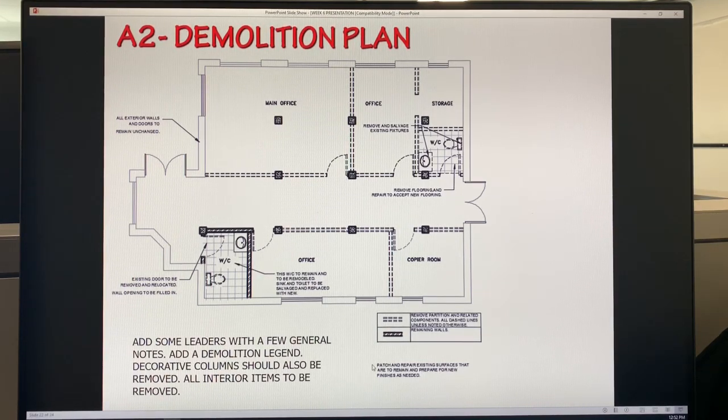Also incorporate some notes like this: patch and repair existing surfaces that are to remain and prepare for new finishes as needed. So things like that. Add some general notes to your demolition plan.